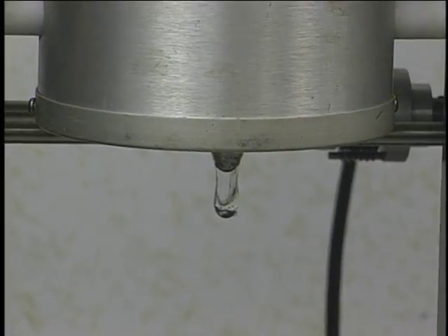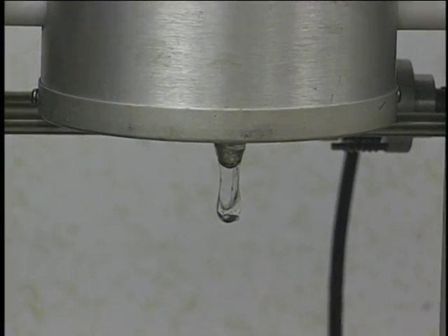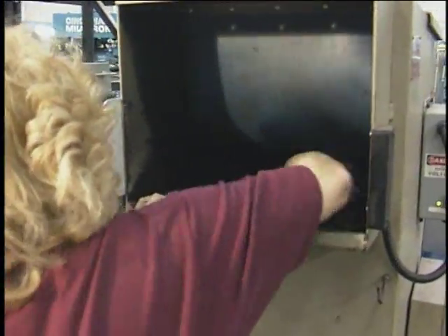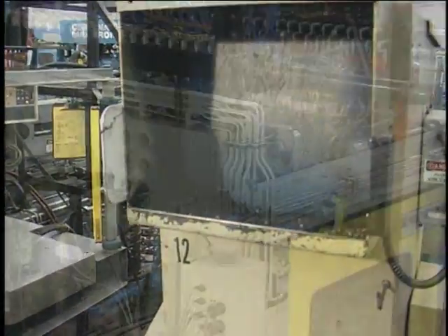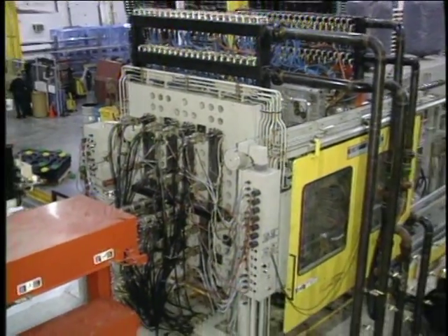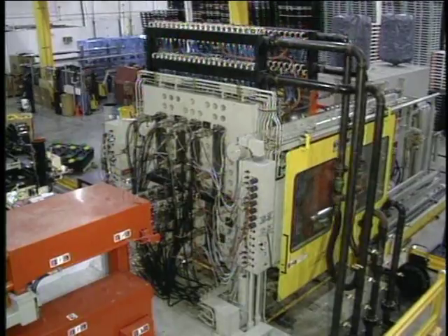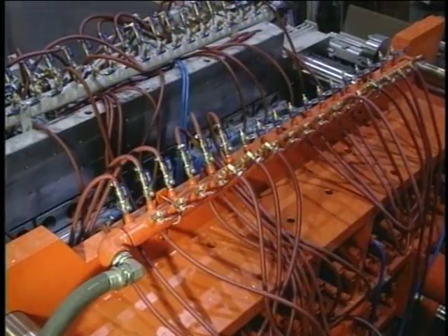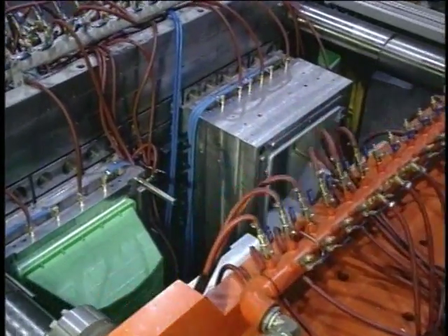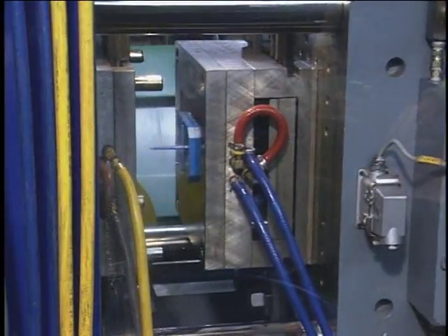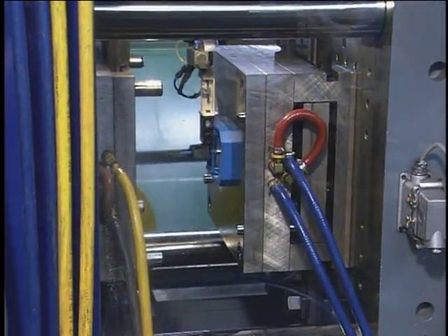Thermoplastics undergo a reversible change from solid to liquid when heated, and can be cooled and reground for reuse over and over again. Thermosets undergo a chemical reaction between two reagents when heated, and achieve their strength through the interlocking chemical bonds. Once molded, thermosets cannot be resoftened. While thermosets are injection moldable, most materials used in injection molding machines are thermoplastics.